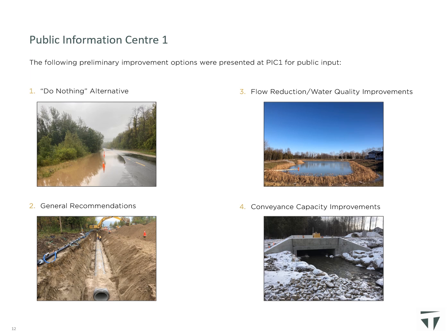General recommendations include improving storm sewer, ditches, and culverts to satisfy town standards, relocating municipal infrastructure off private property and into municipal lands, installing minor drainage systems in underserviced or unserviced areas, and improving overland flow routes.